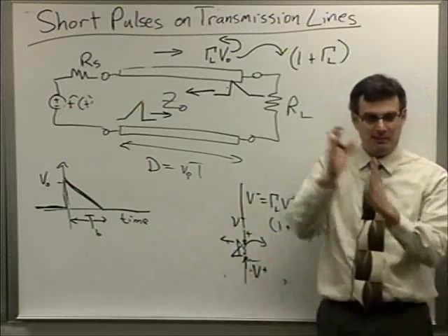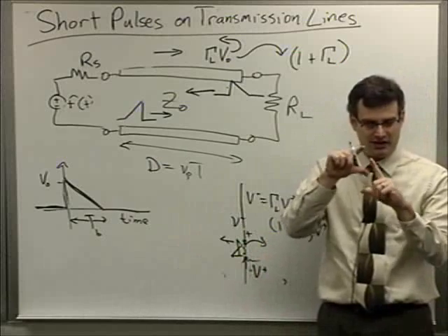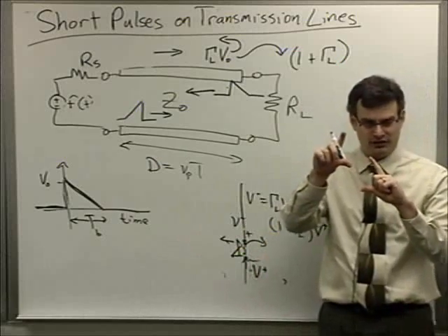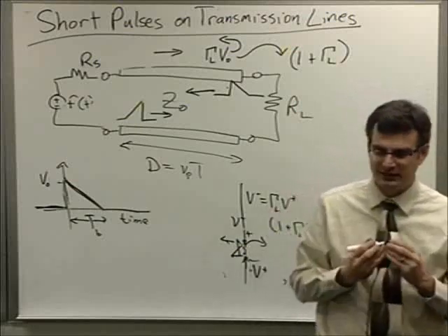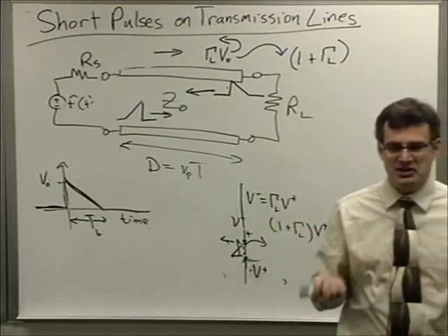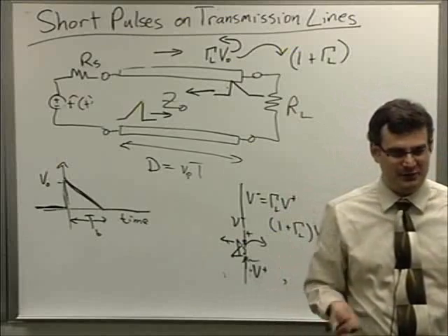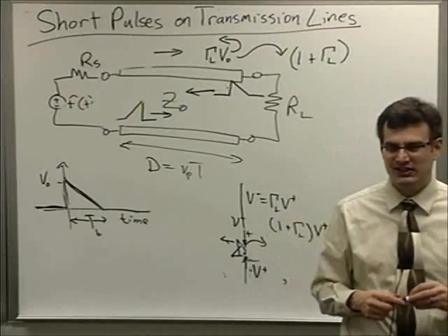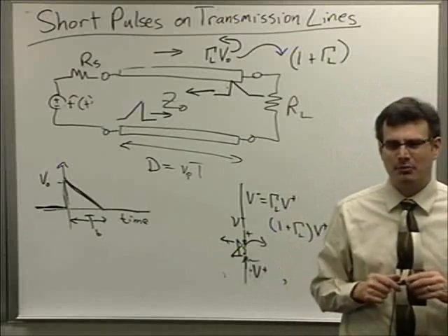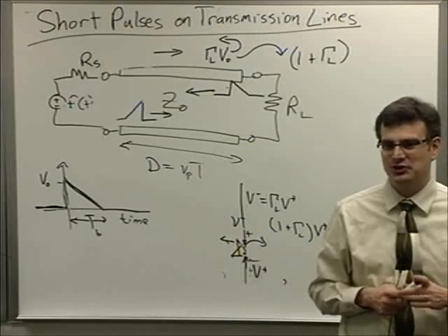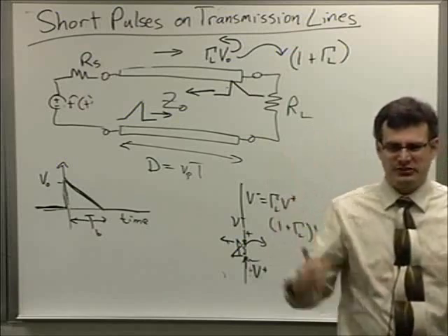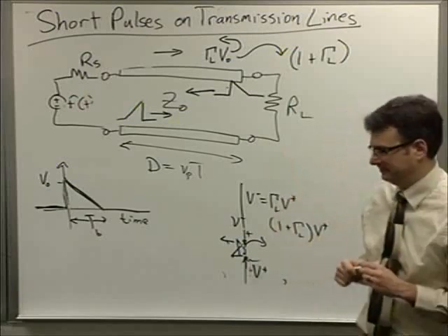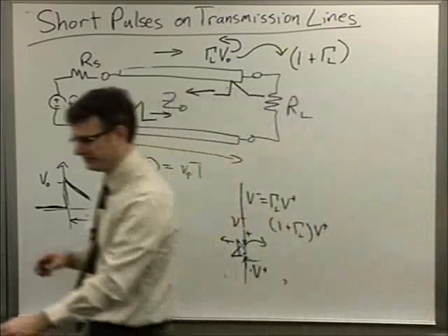And it turns out that at the boundary, all of the voltages will match up, so that the total load voltage on either side of the junction of the transmission line will always be the same. It takes an animation to really drive it home. You can maybe play around with some of the pulses. I think I have a couple of pulse animations on the website that you can look at and gauge what's going on. Good visualization question.